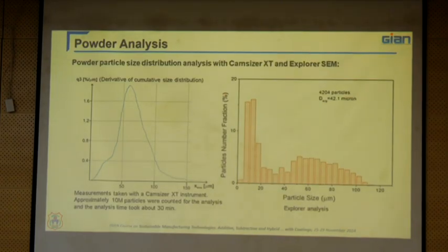And if you see these powder particles, measured with X-ray instruments and laser interferometry, they have got these kinds of particle sizes. Are those powder particles sufficient for additive manufacturing, either PBF or the DED process? We can use them, but here the largest amount of powder particles, the frequency, is in the 0 to 20 range. If you see, for 20 to 100 microns the fraction of powder particles is very small. Then the packing factor, the packing ratio, is going to change, and we may expect so much porosity or voids in the fabricated part, the printed part in additive manufacturing. We need to have a high packing factor. We expect at least 0.9, or 0.99 or 0.98, that much packing factor with a normal distribution of the powder particles.